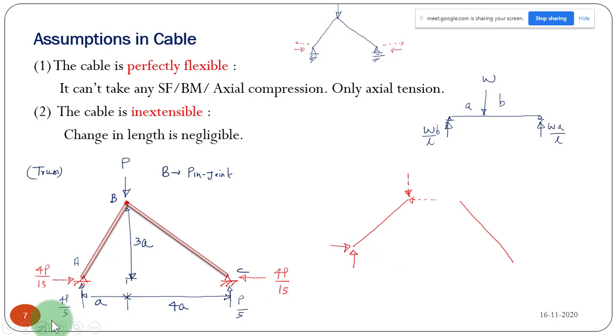Maybe you can say that the resultant will be there, something like this. The resultant of these two forces will be acting along this member. So this member is under compressive force. Some compressive force is acting along this member.